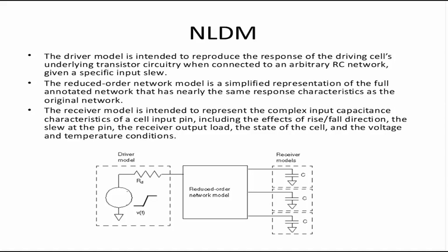As a synthesis and STA engineer, you don't need to be concerned a lot about which model is used, either NLDM or CCS or something else. These are tool-related things, and they go in conjunction with the library, the library vendor, the parasitic data, and so on.